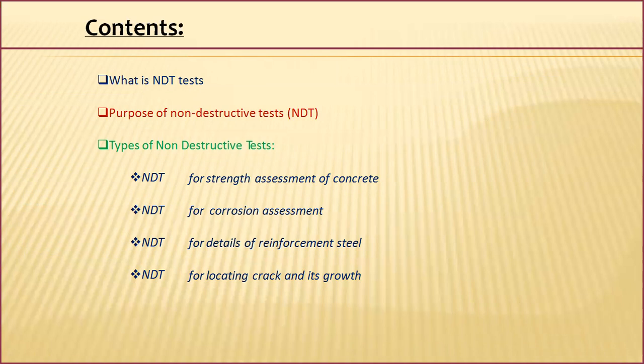It's a non-destructive testing process which doesn't have direct contact with the objects. Upon inspecting the objects for defects within them, we come to know there will not be any destruction of the working process or work specimen. That's an NDT test, and similar workpieces can be examined in various NDT processes such as magnetic testing, eddy current testing, infrared testing, ultrasonic testing, as we have discussed in the rest of the 5 units of this syllabus.